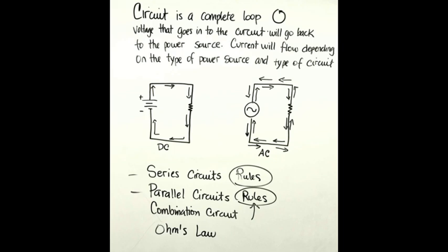Okay, so let's go ahead and apply or look at formula number 3. Now, formula number 3 is a little bit confusing, but let's go ahead and start. Formula number 3 tells us that if I want the total resistance of the circuit, and I have more than 2 resistors, but I have all of the values of the resistors, I have to use the reciprocal.